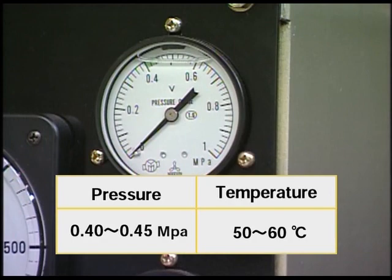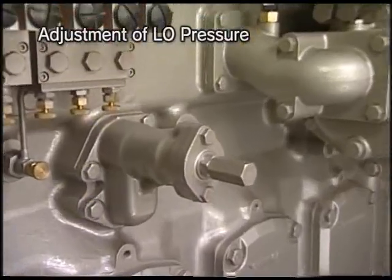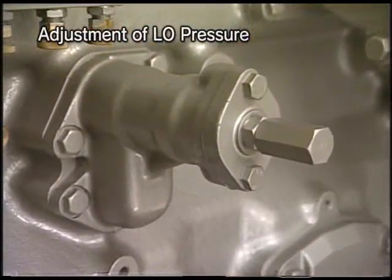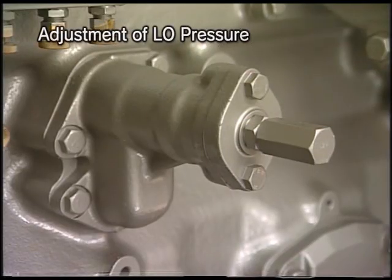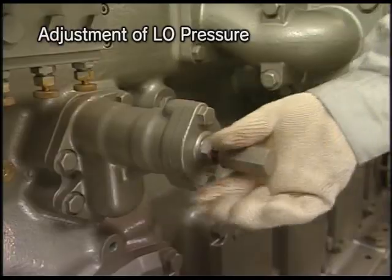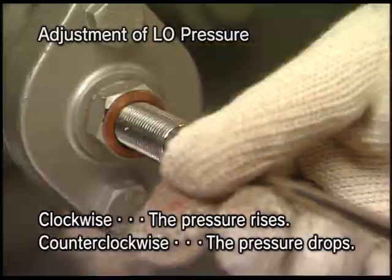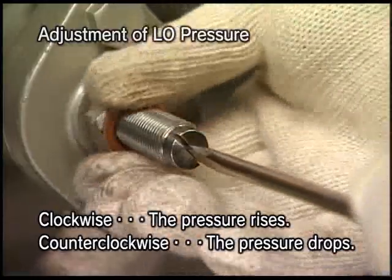Here, I will explain the procedure for operating the adjusting valve of the lube oil pressure and thermostatic valve on the engine side. First, I will explain the procedure for operating the adjusting valve of lube oil pressure. Remove the cap nut and loosen the lock nut. Make adjustments in screwing the adjusting bolt and adjust the pressure.